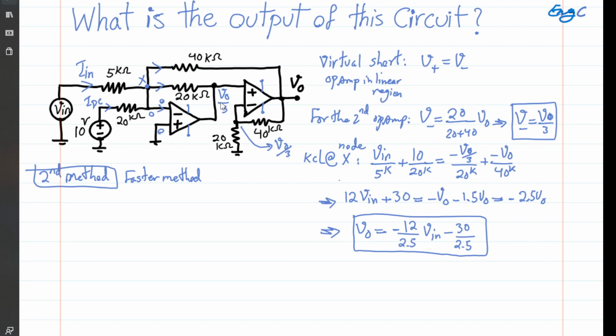So if we want to emulate this circuit or have an equivalence for it, we can show the circuit like this based on one op amp effectively. We have the first op amp that is shown here, negative and positive terminals, with the positive connected to ground. What we can do is, instead of 20K, I'm going to show as if we have 60K. So let me write it below: as if we have 60K, 3 times 20K, but as if we are at V out.